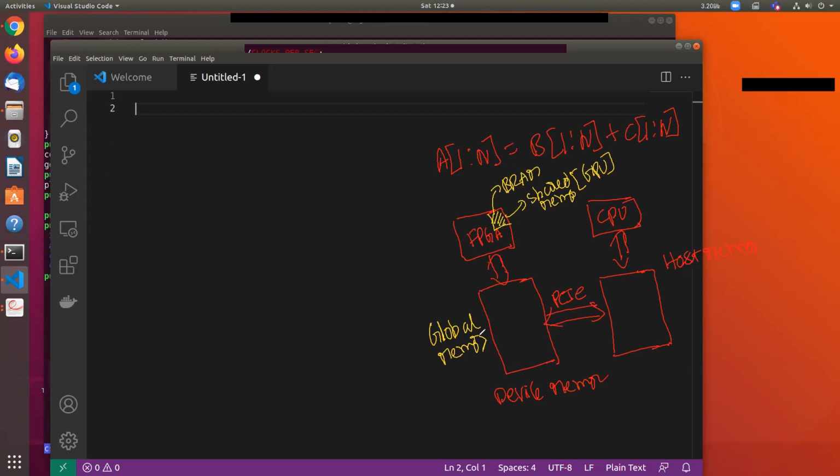So you want to move data from the global memory to, I will rephrase it. When we are doing computations, we would like to minimize the memory traffic between the FPGA or this accelerator and the device. All the hard work that you will do in this course, or in any design, is on how we minimize these data accesses or memory accesses to the global memory. That's where all the hard work goes.